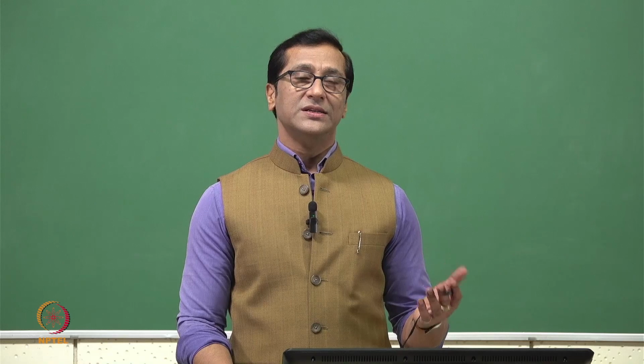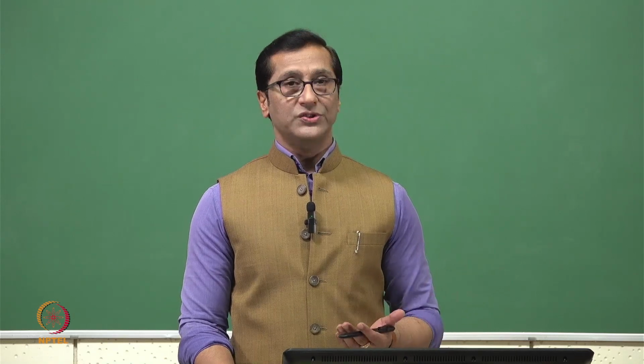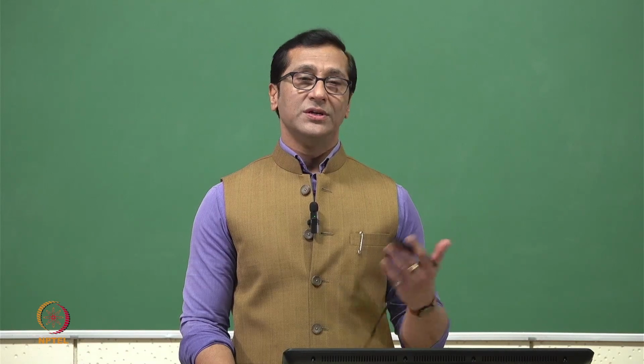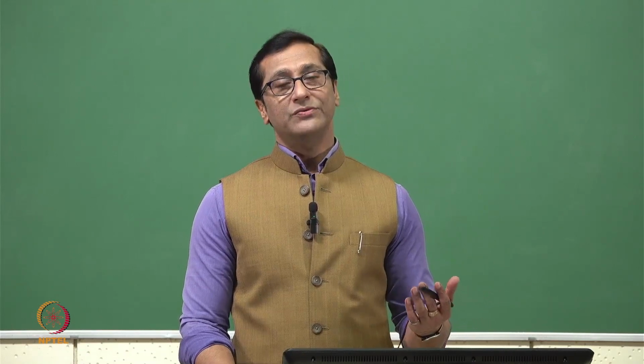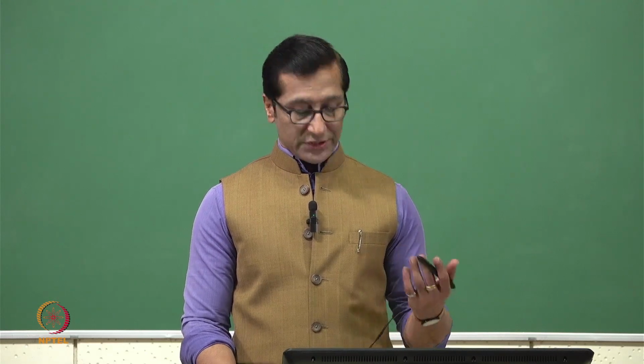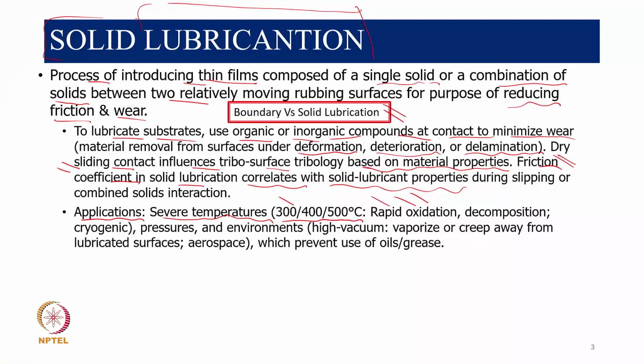If they get oxidized, naturally they are not fulfilling the function, and deterioration will be faster. Because of oxidation and some free ions, even the surfaces will get oxidized or deteriorate. So there's no point in using those liquid lubricants or grease.